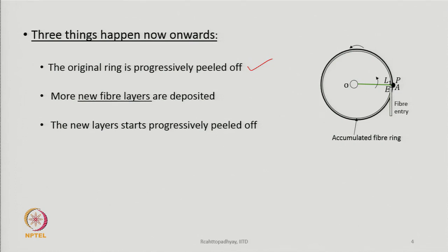That is, there is a little time gap between these two. We must feed the fibers first, and then only we feed the seed yarn. So, the seed yarn end must see the fibers existing in the rotor groove. If there is nothing there, the seed yarn end will not be able to get entangled with the fibers.